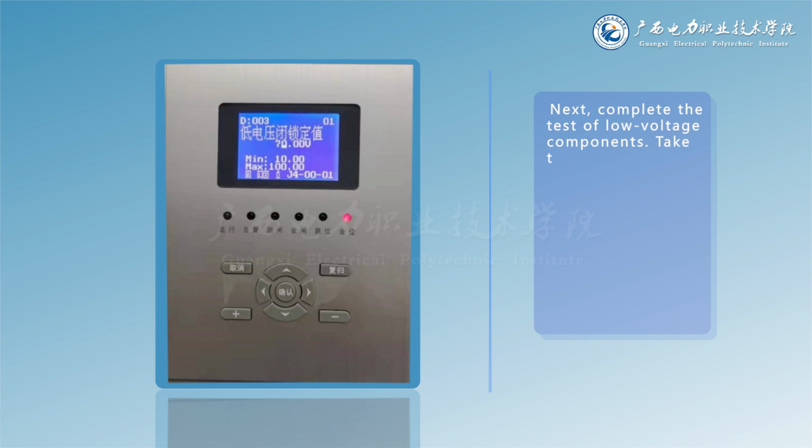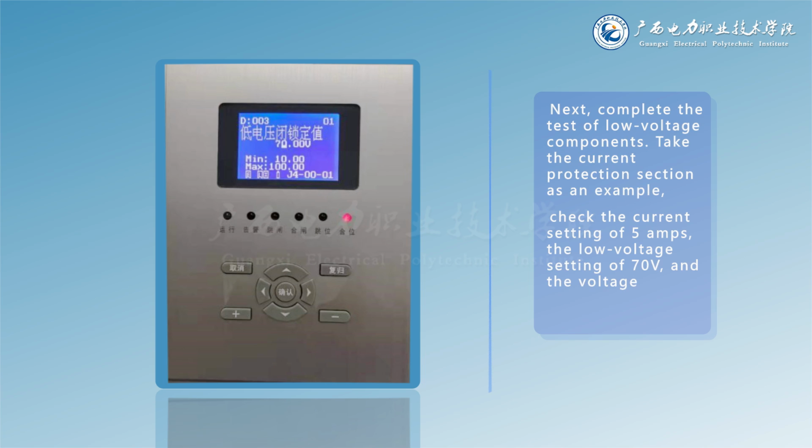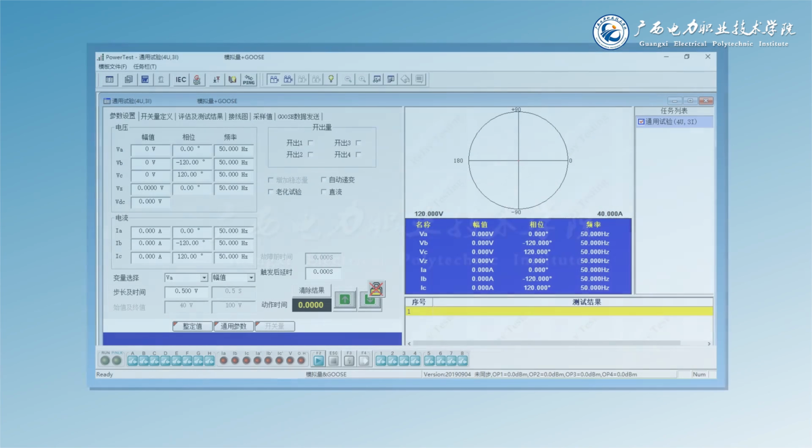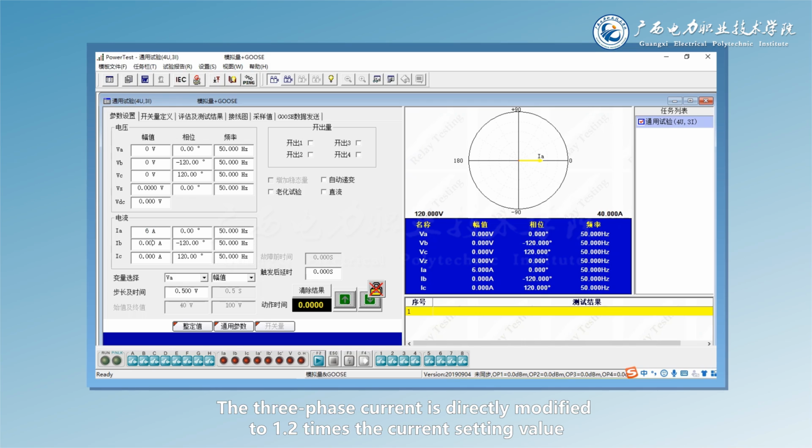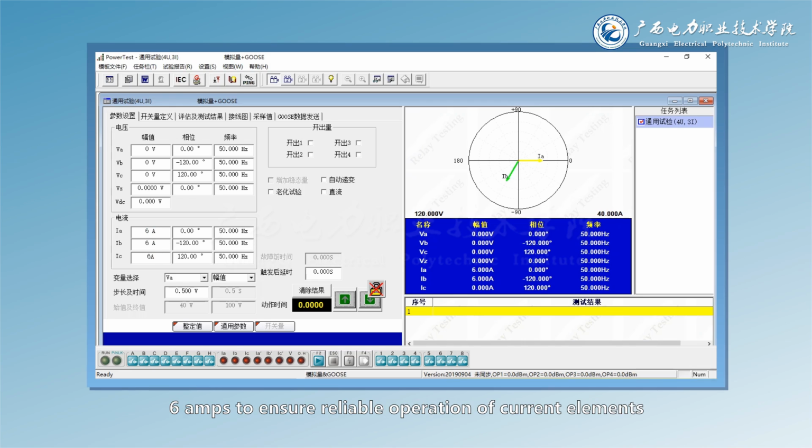Next, complete the test of low voltage components. Take the current protection section I as an example. Check the current setting of 5 amps, the low voltage setting of 70 V, and that the voltage is line voltage, and put into protection. In the general experiment, the three-phase current is directly modified to 1.2 times the current setting value, 6 amps, to ensure reliable operation of current elements. The three-phase voltage is set to 57.7 V.